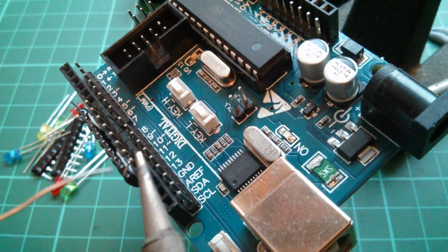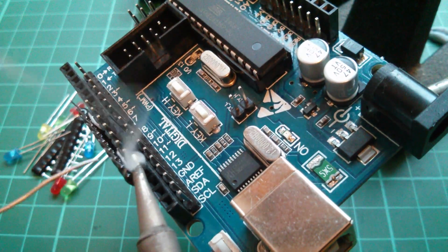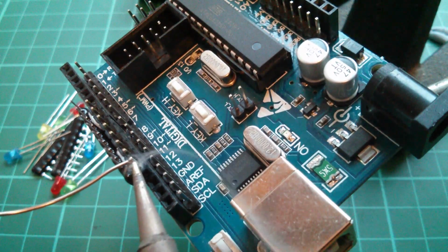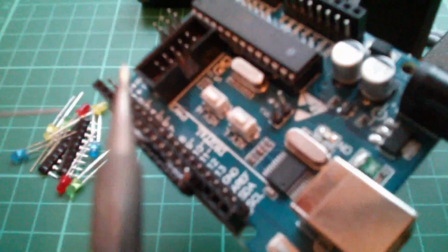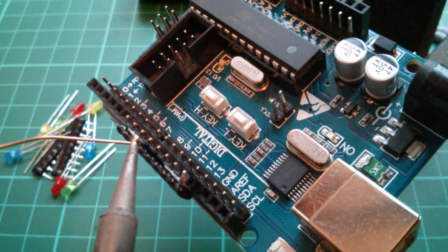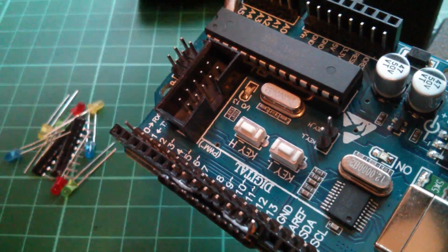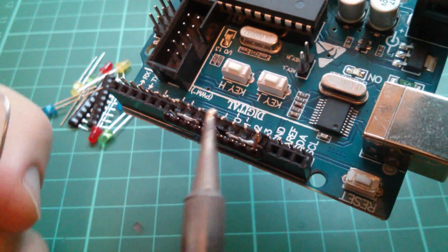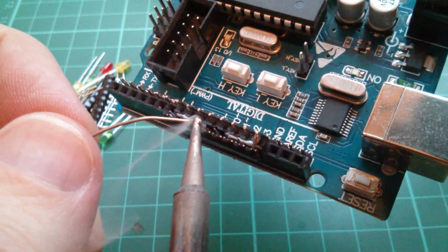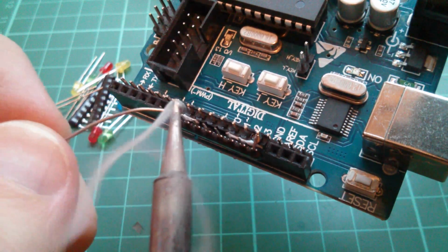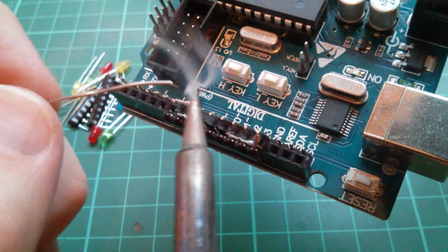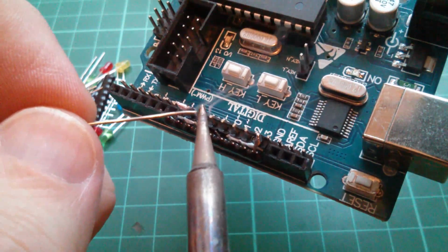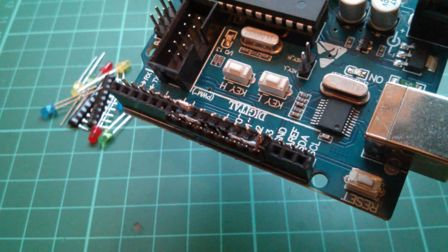So let's first solder the common pin of the SIL resistor onto the last pin of the header here. So that's ground. So that kind of anchors the resistor to the header. Now I'm just going to tin the 6 connection points for the LEDs. Can't get to that very well. Let's bring that round a bit. So 3 points on the SIL and the 3 end pins. Whoops, I'll fix that in a minute. The 3 end pins on the header.